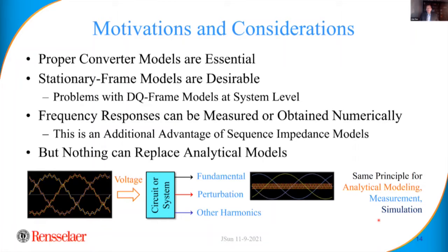And practically, simulation is a very common method now, because with big turbines, it's hard to measure the impedance in the lab. But you can build a very detailed model and then use numerical simulation to scan the frequency response. So that's kind of very common practice. However, I want to emphasize that nothing can replace analytical models.